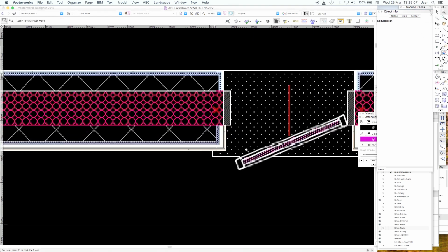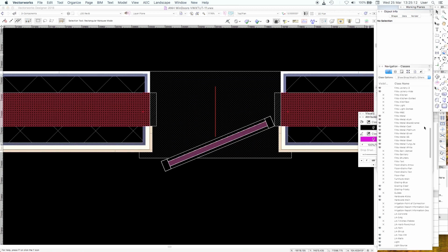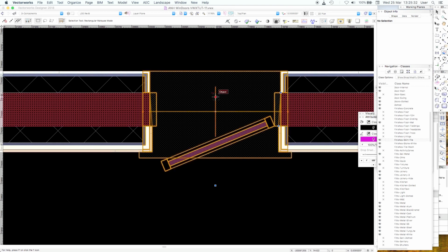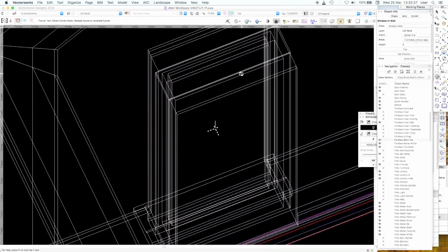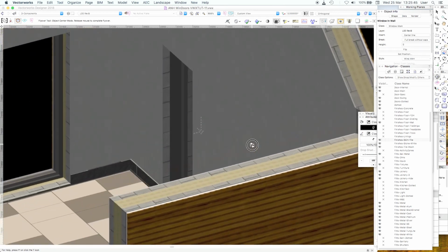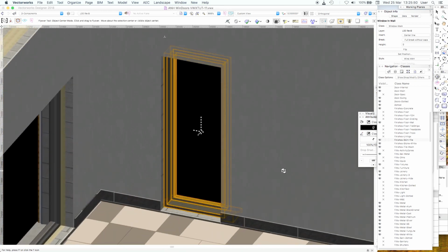Okay. And I suppose that skirting I was talking about is in a layer called finishes skirt tile. Yeah, so no, you see, if it goes away, it just looks a bit funny, doesn't it? Anyway, so that's a drawback. What would I do? I mean, I would just use a wall style that doesn't have a skirting. Maybe I was just trying to be too clever with that. Although it's nice to see it, and it's often left off. And I found one way of doing it was to incorporate it in part of the wall style. And there it is. It does add a sort of completeness to the model. And you can see, it's not returning in 3D.